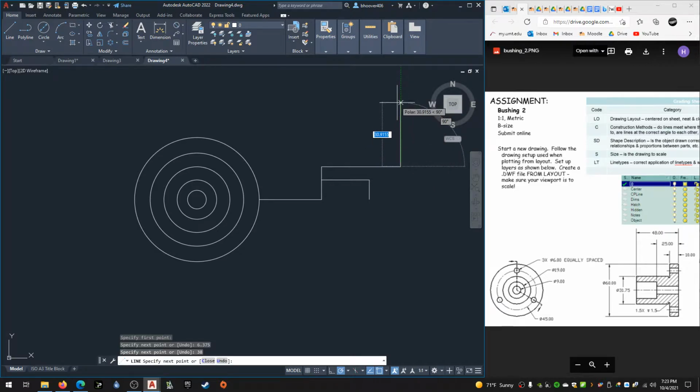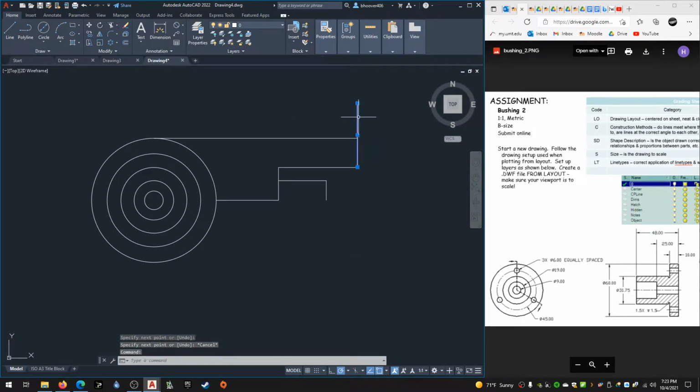And then now I can just draw this up and then project from here to there to get my height. Snap this back down with the blue squares. And then L enter to get this, which is 10 millimeter. And then I can come down, my outer circle 60. So if I come down 30, notice that lines up with the center.